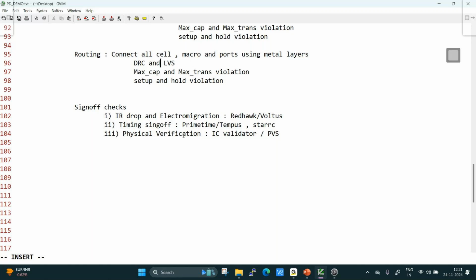See, even though timing signoff I am doing here, fixing here is of no use. Again, I have to fix back in Innovus, because that tool only can write the GDS. Here, this tool cannot write the GDS. Here only we can identify what the issues are and what the methods to fix are. We can mention to the physical design team, they will fix it. So even in companies these teams are separate. They will take your block, see what the issues are, and tell how to fix it. They'll give ECOs, and you have to fix by using ECOs.